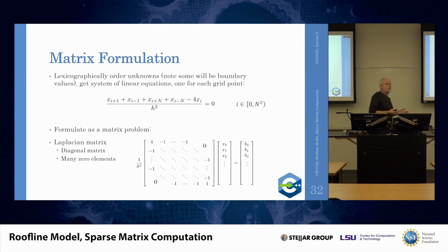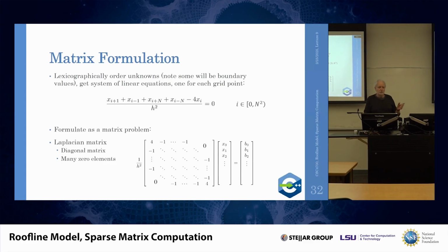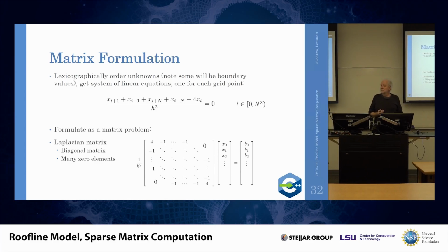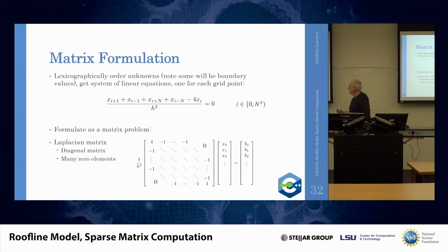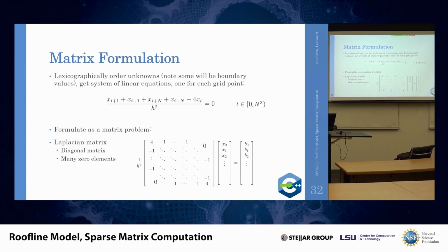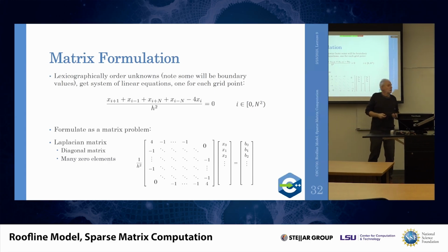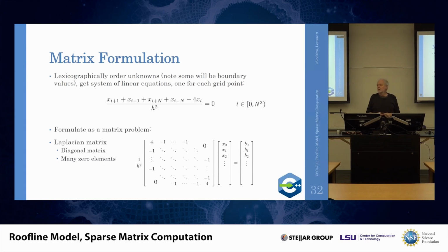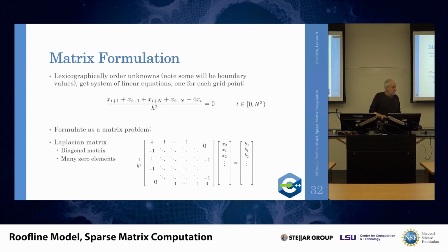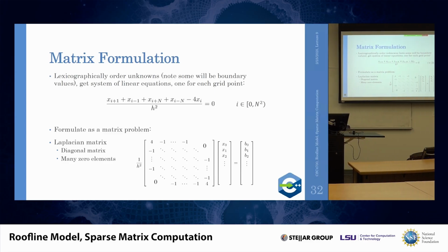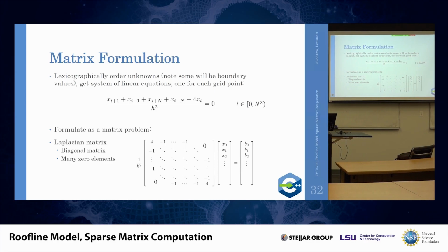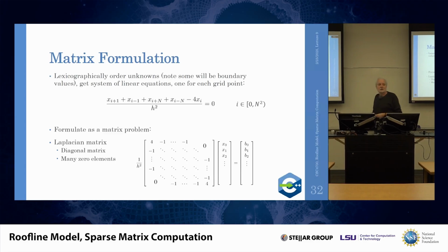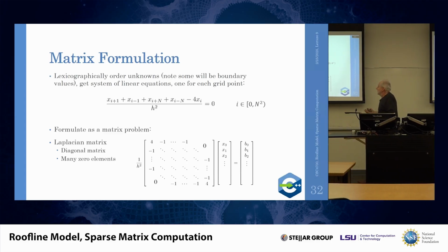Just assume we have our unit square. We want to discretize it with a discretization level of 100 elements in x and 100 elements in y direction, or i and j direction. That means that matrix will have 100 rows and 100 columns. But only 4 or 5 values on each row and 5 values on each column are not 0. That means 95% of the matrix is empty. It has zeros in there. And this is exactly the problem I want to tackle in this lecture. So a bit more lengthy introduction into the problem, but here you go.